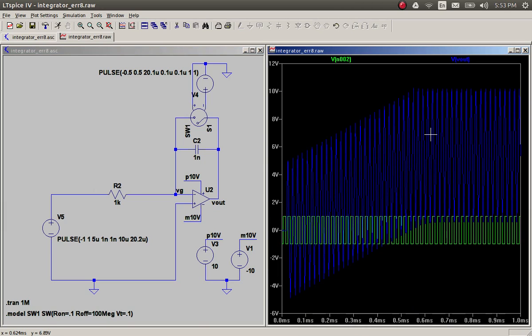The result is accumulating up, which means this is a ramp. This is an integrator. So if a DC integrates into a ramp, there must be a DC in the input that's making the output ramp up, and then of course it gets stuck at 10 volts. That part we know. Once it gets stuck, it just keeps going back and forth. It can't cross 10 volts because my input supply is 10 volts. It can't cross the supply. If you have a realistic op amp, it won't be able to cross the supply minus 1 volt or something like that. Okay, so there must be a DC component in the input.